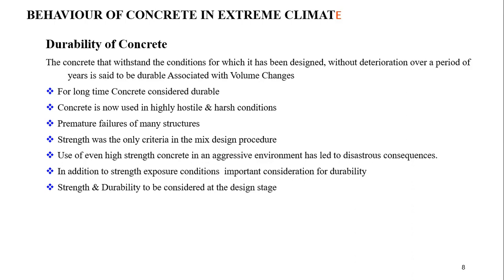harsh climatic conditions also. Next one, premature failure of many structures. So premature failures should be avoided. And strength was the only criterion in mix design procedure. So strength is the only term which is used in the whole of the topic. That is, it should have more strength. The next one is use of even high strength concrete in aggressive environment has led to disastrous consequences. In addition to strength, exposure condition, strength and durability to be considered. So in addition to that, you have to consider both strength and durability of that material.